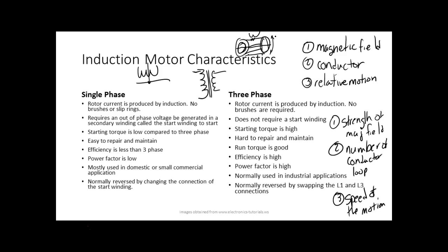The formula for single phase power, of course, would be VA equals V times I. For three phase, it's going to be equal to V times I of any phase times the square root of 3. So basically, if I can split my power over three phases, or the current. We'll talk about delta and Y.